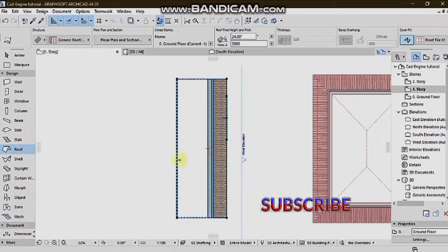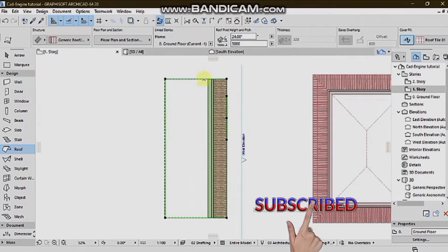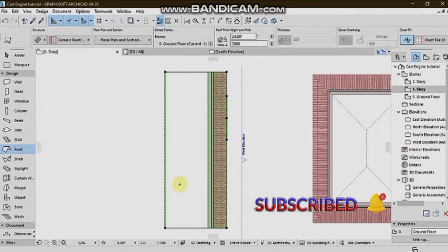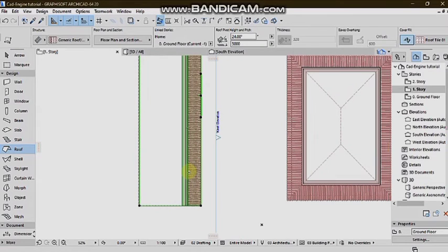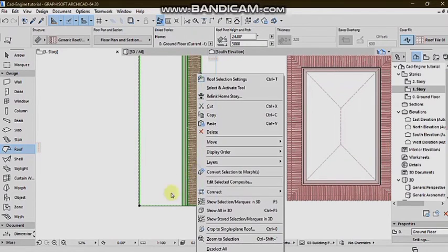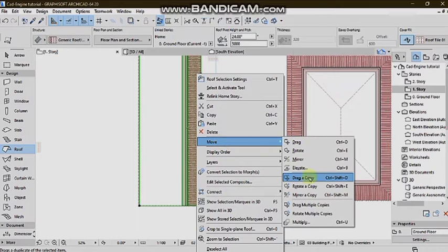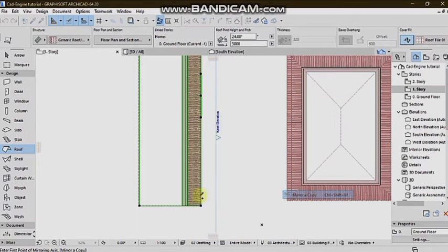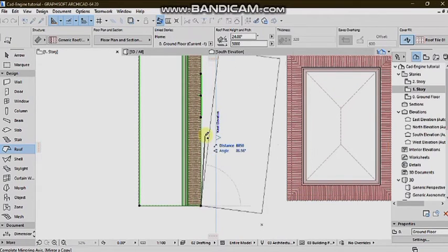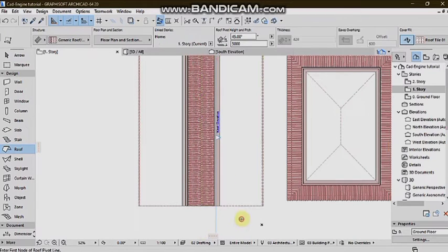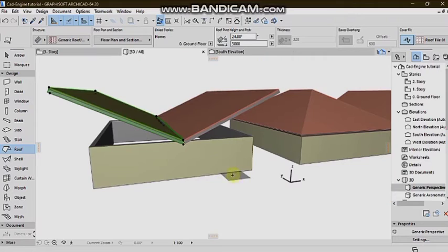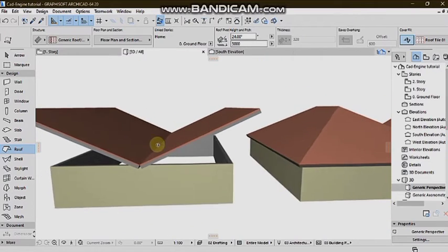We'll go up a story so that you can make an offset of this, so that you can make a mirror of that. Mirror a copy. Make sure you are holding the shift key so that it will stand directly opposite the other one. Now we have this roof.